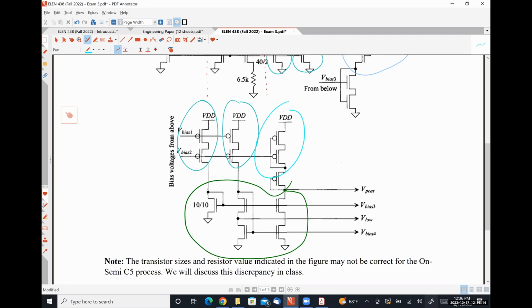After we finish up this project, then we're going to talk about the differential amplifier to move into the single stage op amp, which is nothing more than a differential pair loaded with a current mirror. And then we are going to talk about frequency compensation and then attaching our final stage, and then we are done. So this is probably the most complicated part of our op amp design, and it requires the most attention to detail, because if we get any of these 8 voltages incorrect, our circuit won't work. Okay,